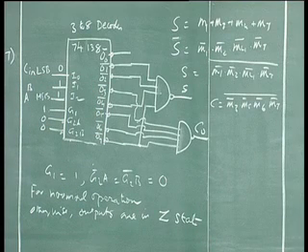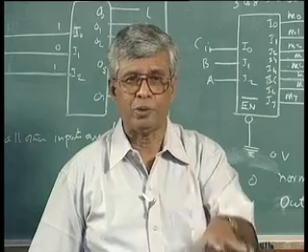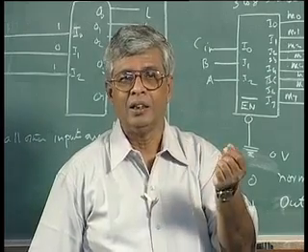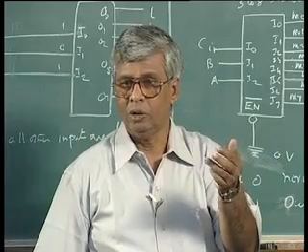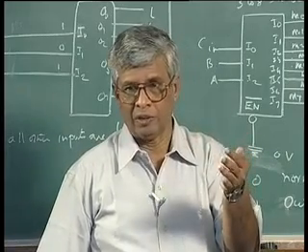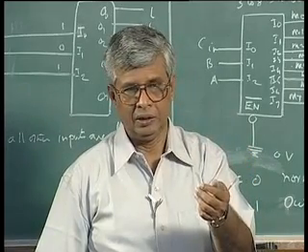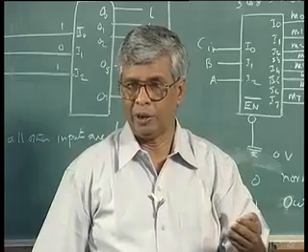Some of these practical things you should know, that is why I thought I will introduce this. When you look at a circuit, logically you may be right, conceptually you may be right, but it will not work, because you are assuming the outputs will be active high, but they are really active low. Or you did not know there was an enable which has not been properly connected, or you did not give the proper power supply voltage and ground.